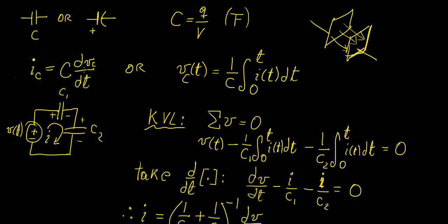This is why capacitors and inductors, as we will see in the next video, usually only work in devices where the power supply is not constant, so it is changing with time. But you can still use them in different senses. So in here I'm just going to denote this as a generic power supply, so this could be a function of time. And if we wanted to express the voltage or the potential drop across the capacitor as a function of time, then we can rearrange this equation by integrating both sides with respect to time, and then essentially this is what we end up with.